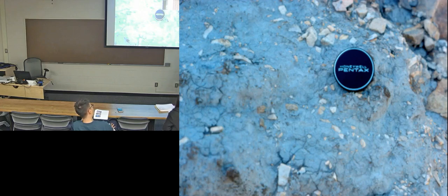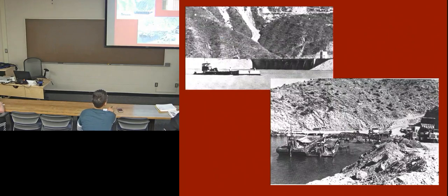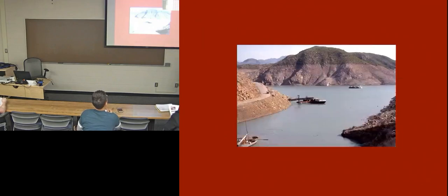And so the intended expectation, I should say the expectation from silting by all this rock flour, happened. And it's going to be an advantage because it's going to clog up that blanket and make the flow net work even better. But in the meantime, we've got 500 of these sinkholes. Well, it was thought that they better be filled. So a whole project, several $1 million, was required to buy these bottom dump